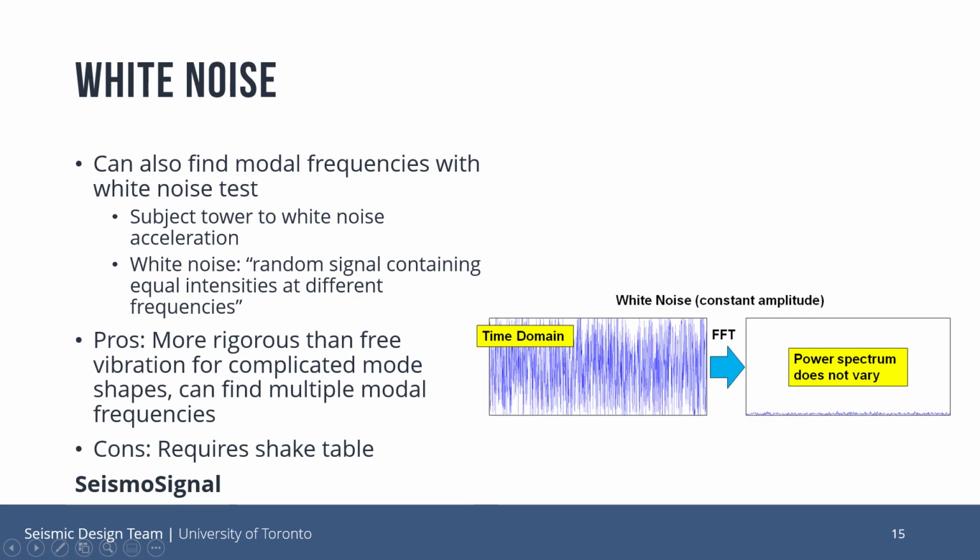So this is a little more rigorous, and we can find more mode frequencies for more complicated mode shapes, but the con is obviously it requires a shake table, and there's more hardware required.